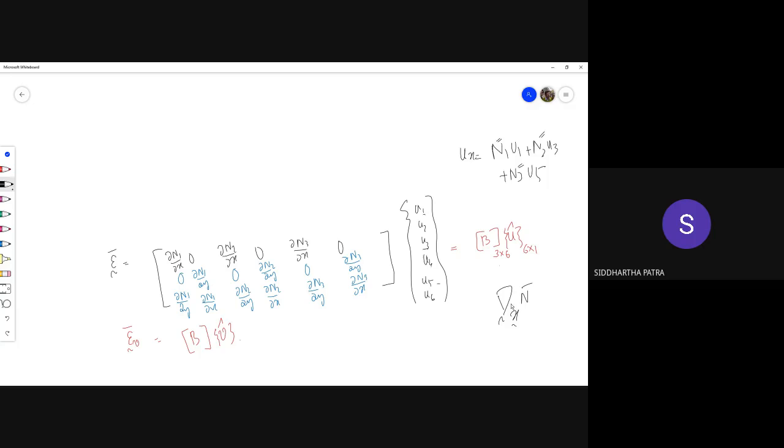So once I calculate the Jacobian, take the inverse of it, and multiply with the gradient of n with respect to xi, I will have the gradient of n with respect to x, and that quantity is populated with each of these terms. So the terms seen in the B matrix are coming from this gradient of n with respect to x. I have to substitute from there.